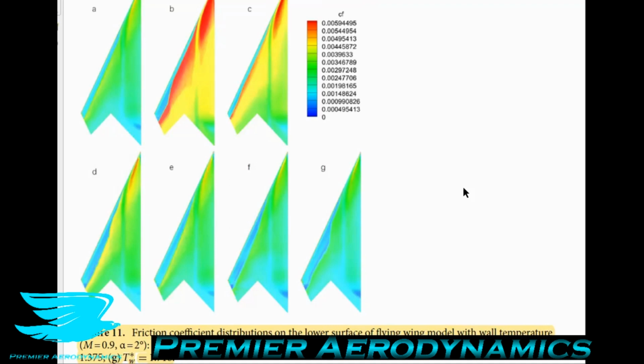The turbulent flow after transition in the case of the cold wall has a larger friction drag coefficient and smaller friction drag in the case of the hot wall. So in other words, the hot wall seems to be much better for reducing drag overall, for a wing at least. I'll get into later why I think it's only just for a wing or a streamlined body.